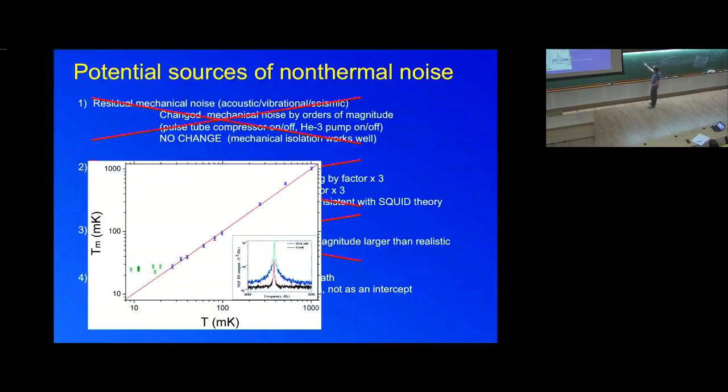So if there is any source of power dissipated inside this magnet, for instance, you will have to dump this thermal energy, and the only path is this, because there is no gas inside, so there is no thermalization to the gas. The temperature is so low that there is no way for the system to cool by black body radiation. The only way to cool a system is by conduction.